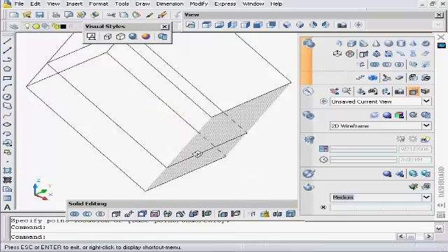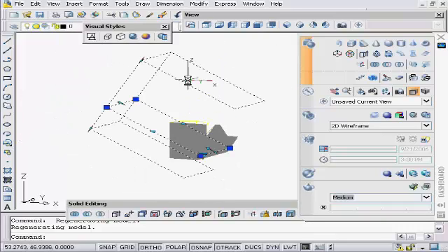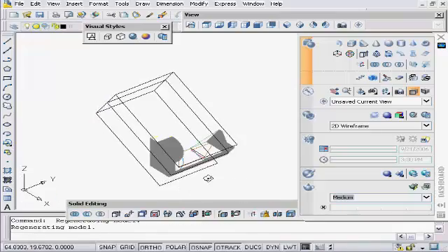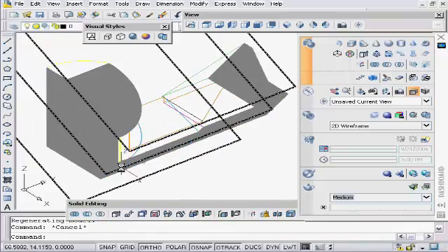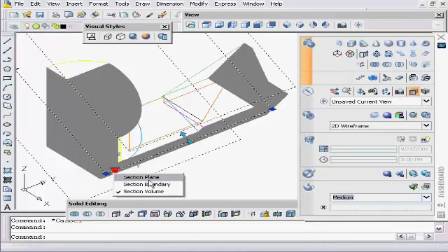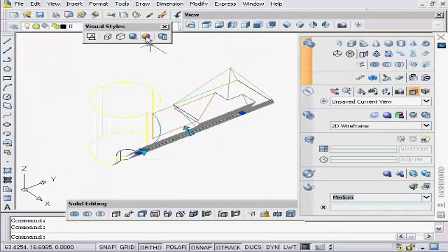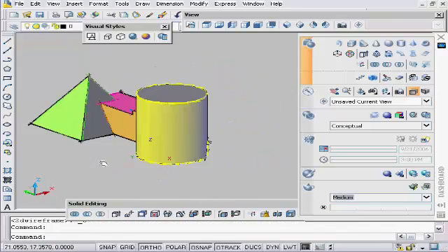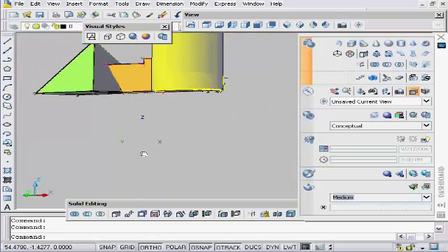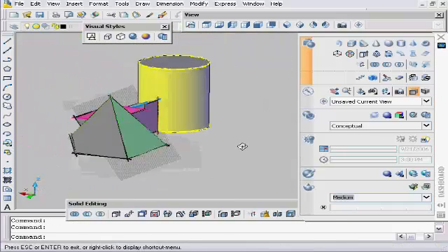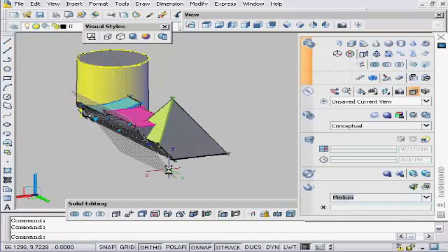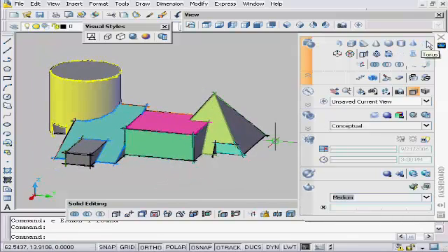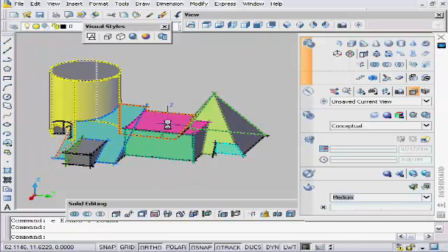Okay. Section boundary. Click on here. I want to see the section volume, which then has a 3D aspect, shift middle mouse button, where you can squeeze it down this way as well. Just insane how many settings we have on here. And back to section plane. My conceptual view, spin that around with my objects where I just used my colored faces. Shift middle mouse. And then again, the nice thing is you erase it and everything comes back just the way you had it.